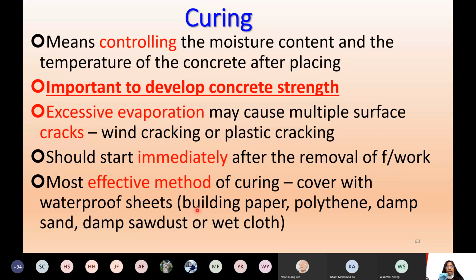Cover between the reinforcement and the bottom, right? Cover between the reinforcement and the bottom needs to be properly checked all through the concreting. Some places the stone has gone out, right? While people are working, the stone will be removed, and by that the reinforcement will go down, touching the formwork itself. In that case, you can see the steel member outside, with no concrete surfacing on top of it. Such things have to be avoided by properly checking the cover at distances, especially at the ends and the middle points, so that the concrete is covering the reinforcement. Cover with waterproof sheets.